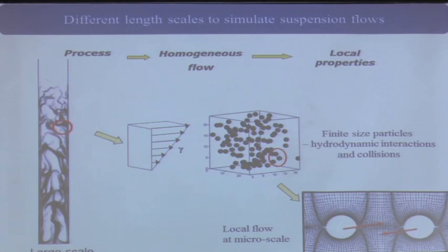There are many open problems in the modeling, because you have new terms. I told you that with turbulence you have new unknowns. When you do multi-phase modeling, you still have those, because multi-phase flows are turbulent, but you also have new problems coming from one-way coupling, two-way coupling, three-way coupling, four-way coupling, and all these bricks that you need to add to your Navier-Stokes equation.